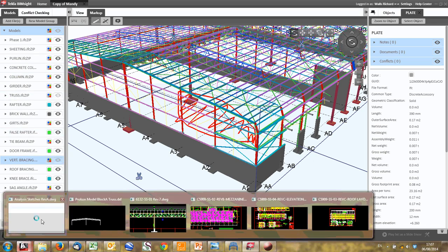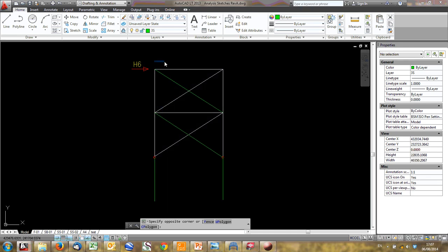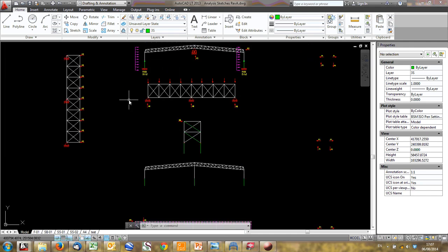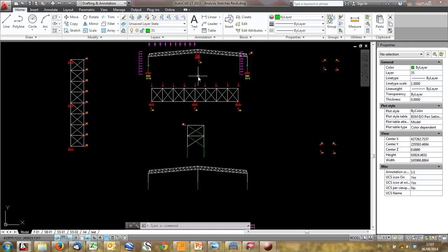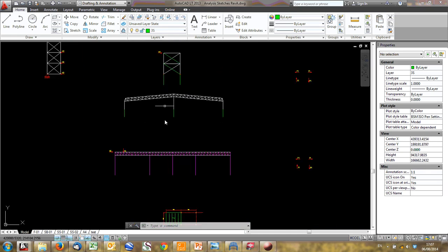Then this acts as a rigid object, this whole top bit. So you just take moments about here. This force times this distance equals this reaction here times this distance. And in three or four lines, you can actually get the foundation reactions very quickly, very easily, without having to analyze trusses and bracing and everything else. You can really break it down into something that you can approximate the design for.